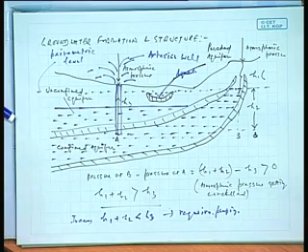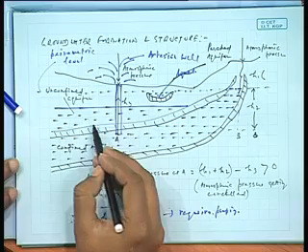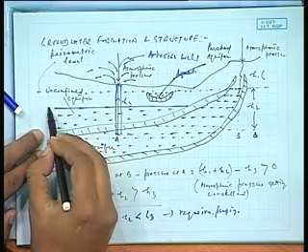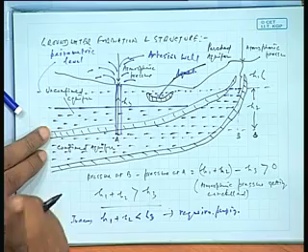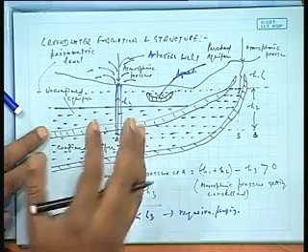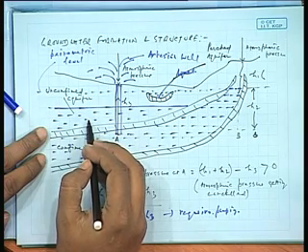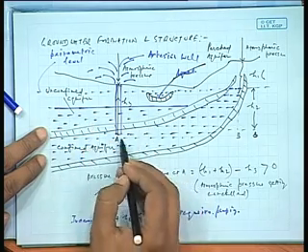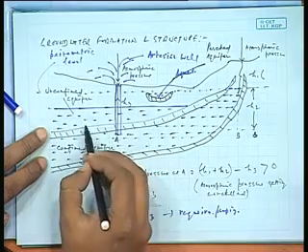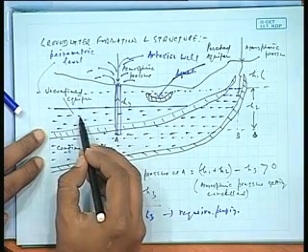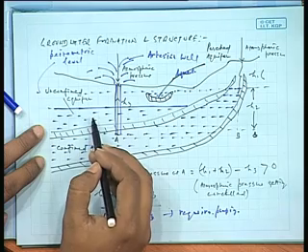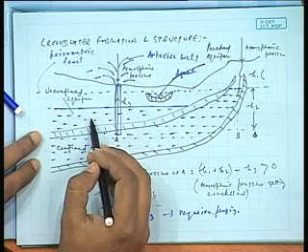And as you can see here, an artesian well cannot take place in an unconfined aquifer. Remember this. At any point of time, an unconfined aquifer cannot give rise to an artesian well. It has to be a confined aquifer. Only when the water is under a pressurized condition in a natural setting is an artesian well possible. Otherwise, we find an unconfined aquifer, and whatever water we may have, that water cannot be derived without pumping.